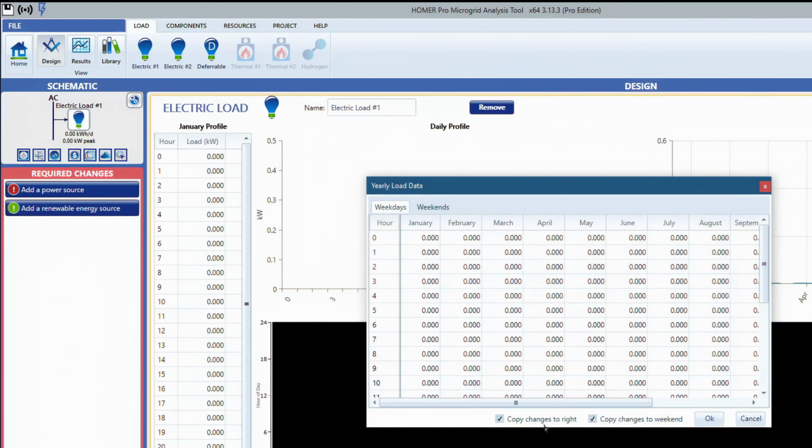First of all, one ventilator of 60 watt operating from 9:30 a.m. until 11 p.m. Okay, so here there is no 9:30. I cannot enter 9:30, so I'm going to choose just, for example, 10 a.m. So starting from 10 a.m. I have to add 60 watt. Since here we can see that the unit is kilowatt, I need to enter it as kilowatt, so it is 0.06, and that is 60 watt. Okay, so from 9 or 10 a.m.